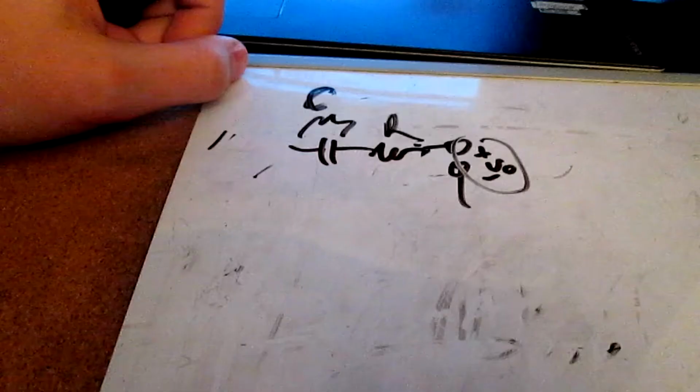So the way we can get rid of that is by getting rid of our ambient noise, as I touched on a little earlier. And that's at a frequency of 120 hertz, so that means we want a high pass filter. So I did some calculations, and I got, so this is what we want to do. I'll draw it out on my whiteboard.